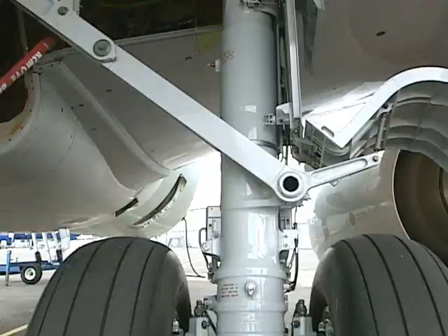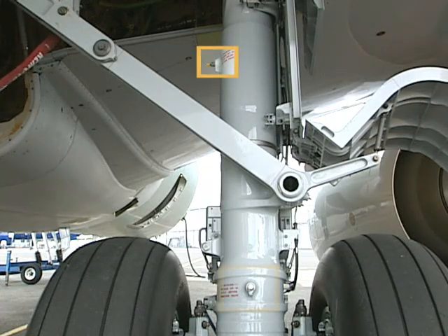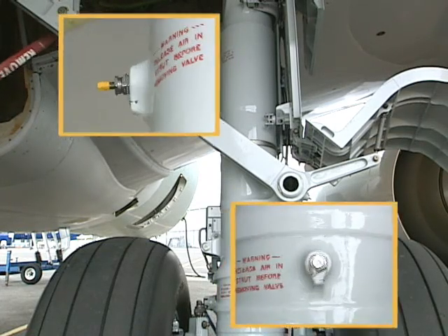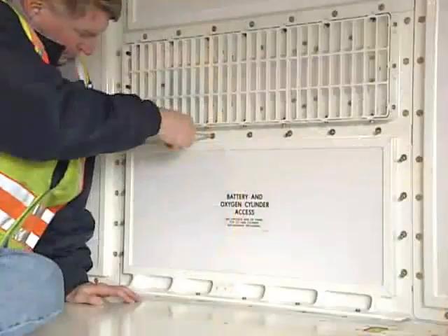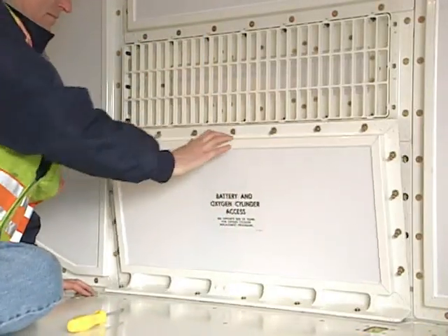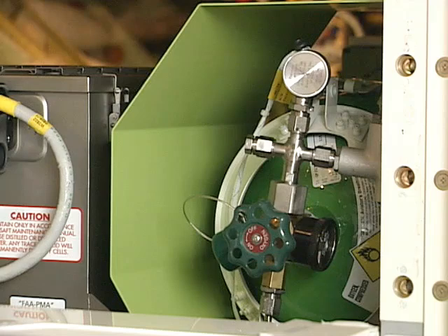Note, if you cannot service any of these systems for flight, you must analytically account for the weight and CG effects produced by any missing fluids.